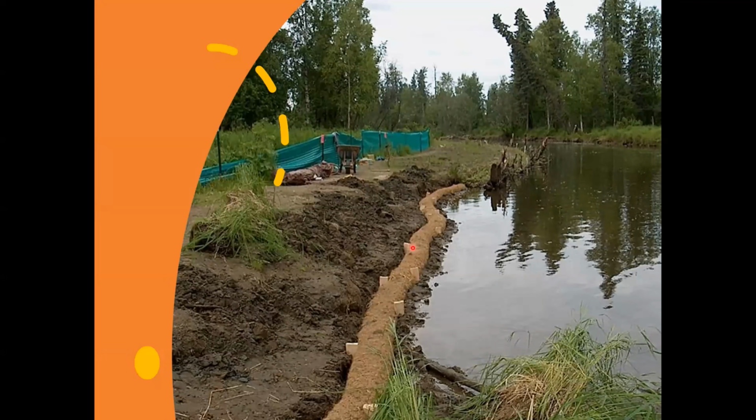So in this case, you can see they had root wads, but they needed to continue on. Because the root wads were no longer needed, they just used a coir log and went back and put some trenched willows in behind this coir log. One thing I like to point out is to look and see that this coir log is actually entrenched in the soil, which means they just dug a hole about half the height of the coir log. So if this is a 12-inch coir log, it's sitting in a trench that's about 6 inches deep. And then they alternated the wooden stakes.